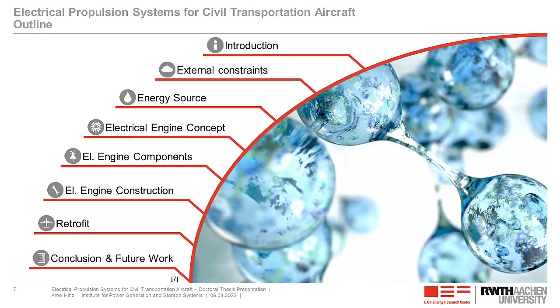Let's go on with the energy source. We will apply hydrogen as the most efficient sustainable fuel, as hydrogen itself is feedstock to synthetic fuels and therefore has a lower power energy demand for production. Further, we will apply that in liquefied form, since liquefied hydrogen has the highest volumetric energy density among the storage options of hydrogen, and comes along with a very low temperature of minus 253 degrees C, which supports the cooling system design later on.